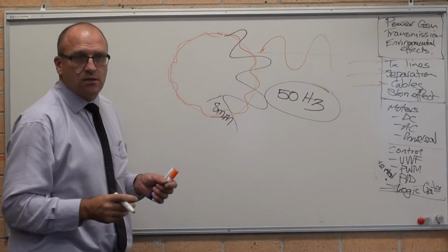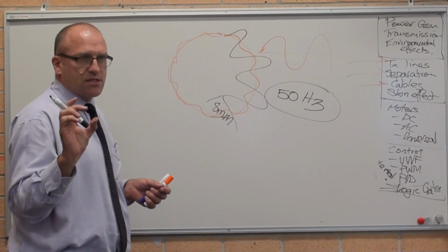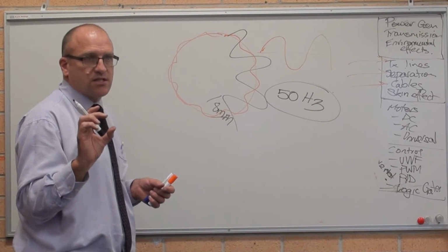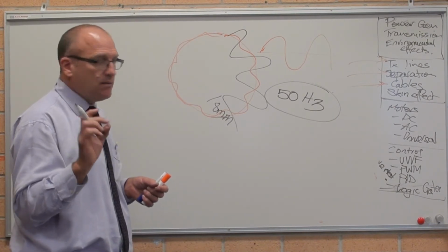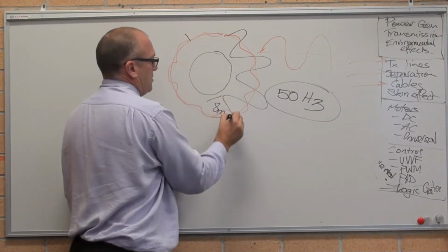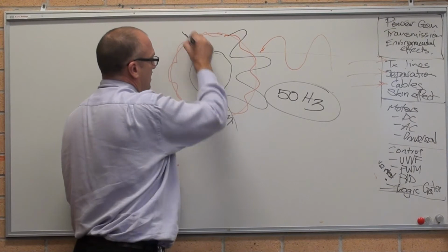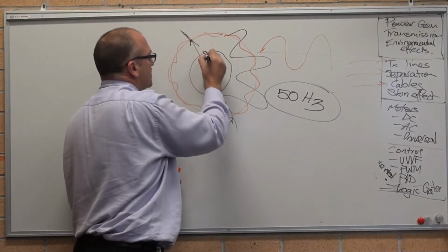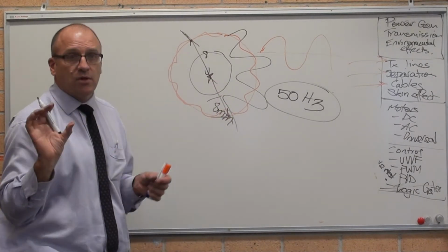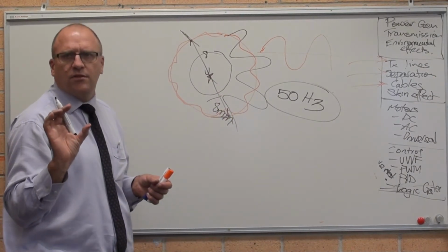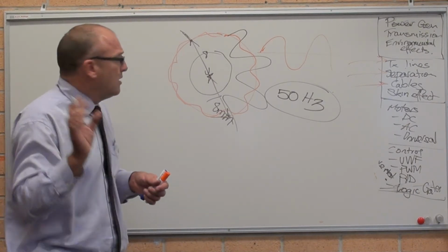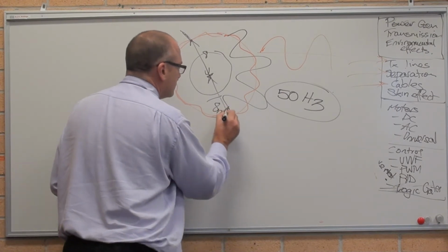So if you've got a cable that's 16 millimetres round, or a solid bar that's 16 millimetres round of aluminium, that will go into the 8 millimetres in there. So that's 8 millimetres going in that side, that's 8 millimetres going in there. The whole cable is used. I think the skin effect for 50 Hertz is 8 mil, isn't it? Give or take. Yeah. Okay. So, does that make sense?